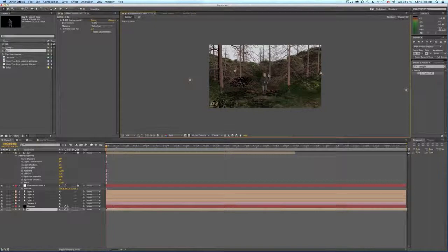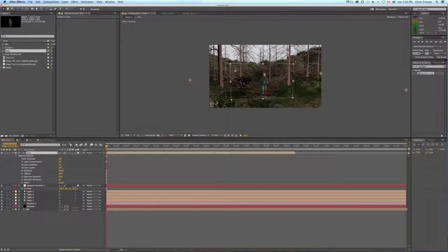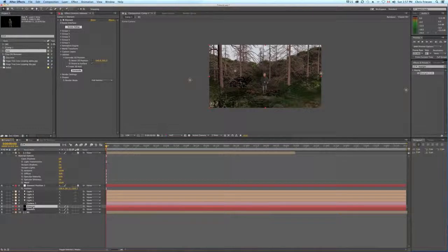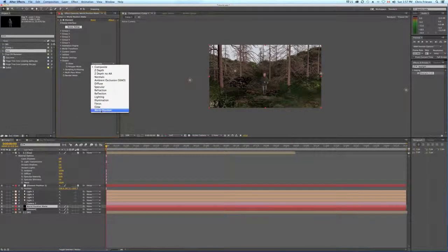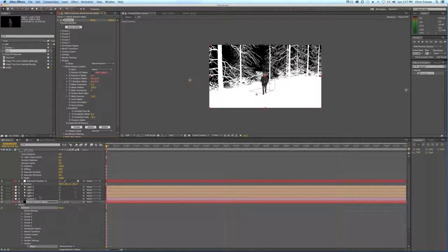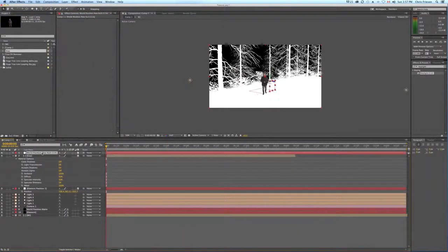top of everything. So when you've got your element layer set up the way you want it, you can duplicate it and come into, on your new one, and we'll call it World Position Matte. And I will come up under Render Settings, or sorry, Output, and go Composite down to World Position. And it generates a black and white matte for you to use. And you can also drop down Create World Position and hit Create to create a null that will control where it is.